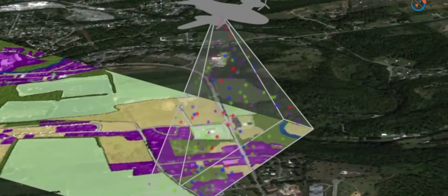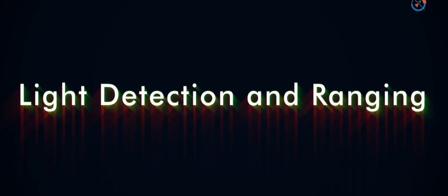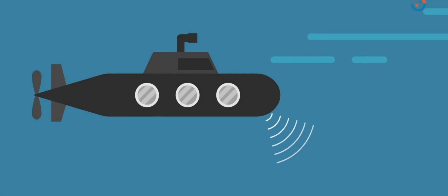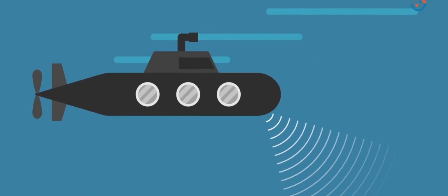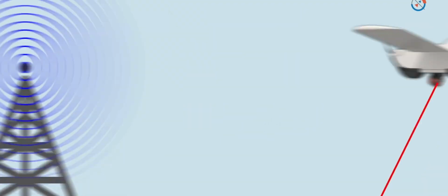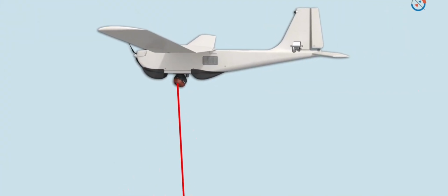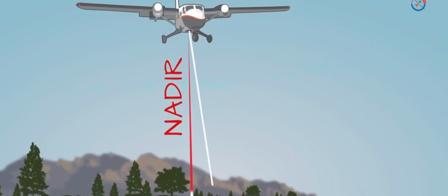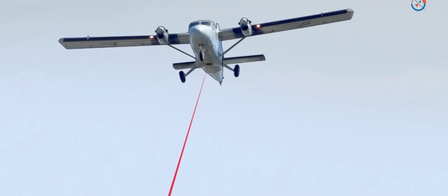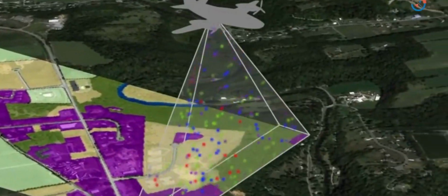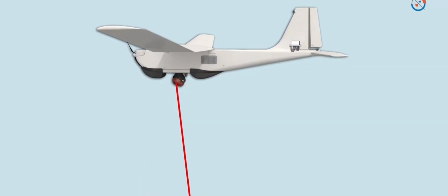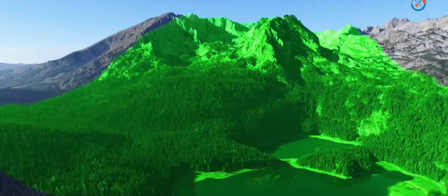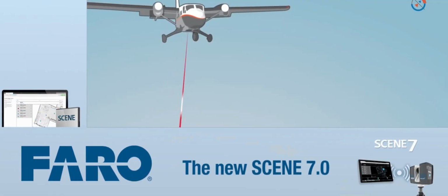Whereas sonar utilizes sound waves to map things, radar employs radio signals. Lidar, on the other hand, makes use of laser-generated light. As the plane travels, a lidar instrument scans the ground from side to side. As a result, while some pulses will travel directly at nadir or in a straight line, most pulses will travel at an angle. Airplanes, unmanned aerial vehicles and helicopters are the most widely used platforms for collecting lidar data over large areas. There are various methods for collecting data with lidar from the ground, air, or satellite.